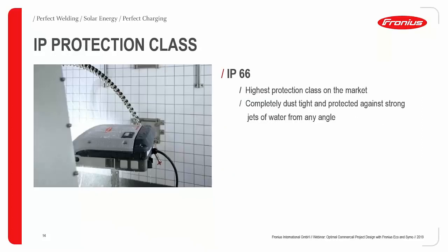Then the IP protection class. Our commercial inverter comes with IP66 protection class. IP66 means it is completely dust tight and protected against strong water jets from any angle. So of course it is suitable for outdoor and indoor installation.